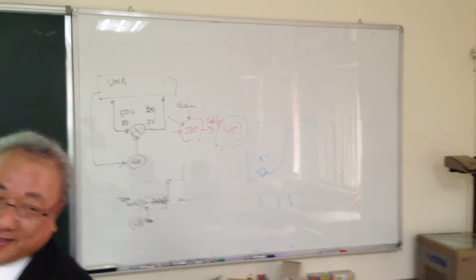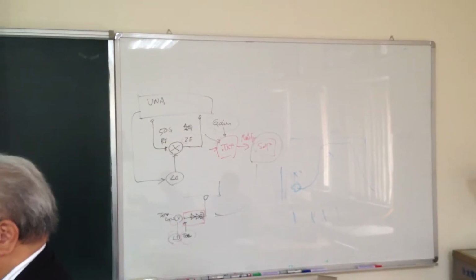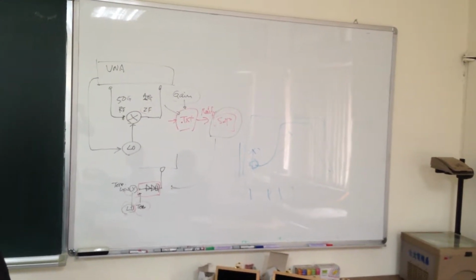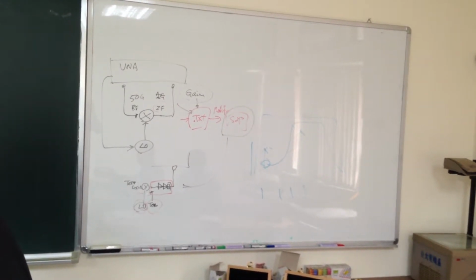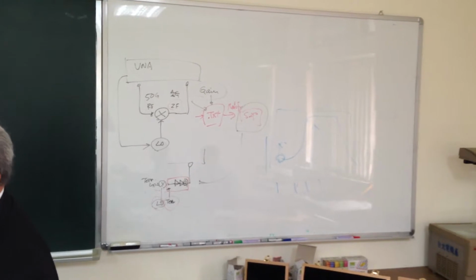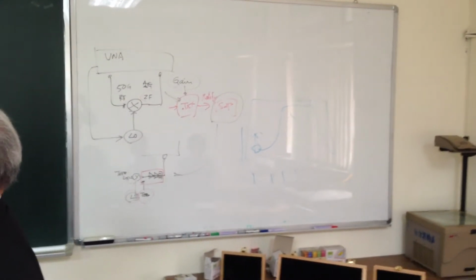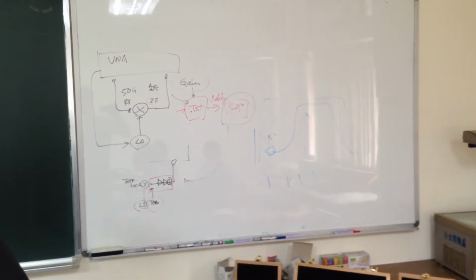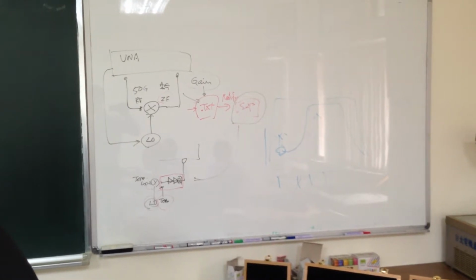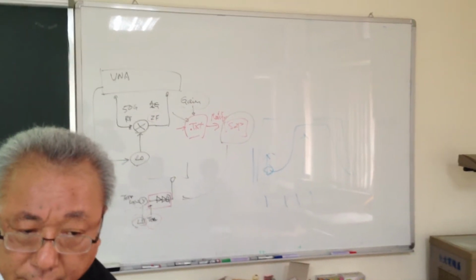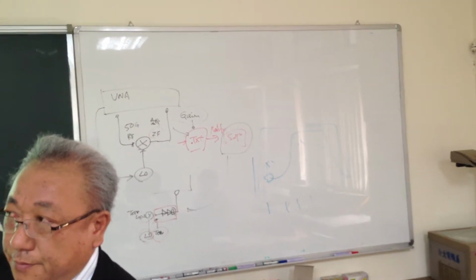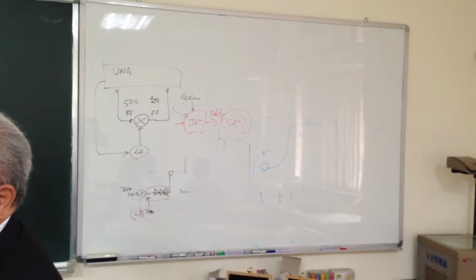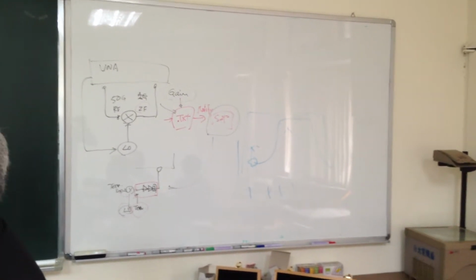Below 30 gigahertz, the noise figure measurement is done in the instrument, not here. This receiver starts measuring noise figure from 30 gigahertz, 30 to 100 gigahertz. So the accuracy is as accurate as the VNA. Below 30 gigahertz, the noise figure is operated inside the VNA mainframe. So we don't need another filter and amplifier when we measure the noise figure below 30 gigahertz.